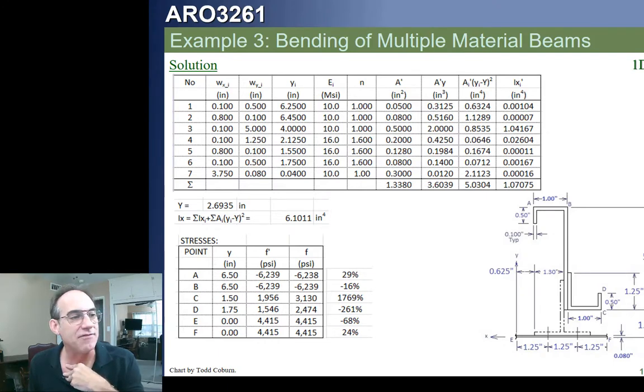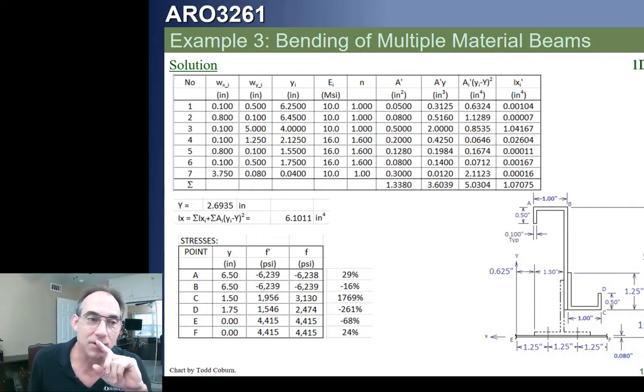You can see the f prime is just that fictitious number before we apply the n. That f is the actual stress. And this is just showing over to the right the relative errors due to this being a non-symmetric section that we pretended is symmetric. It looks like this is total nonsense, but actually the numbers are much tighter than this. They're actually effectively about 6% off, and that 6% is even left when you consider other approximations. Folks that are academics that don't understand real practical structures may be a lot more worried about these numbers. We can talk about this further if you want to.